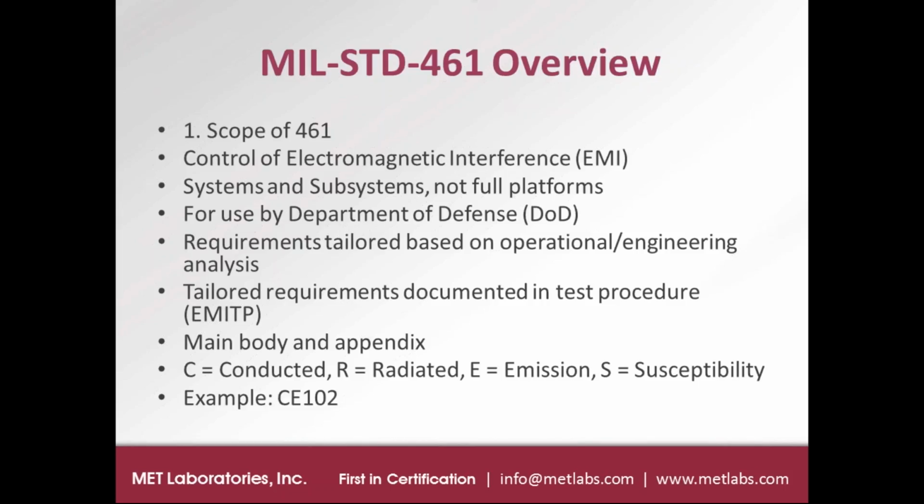The test methods in MIL Standard 461 are named with a five-character name, and the first character, the C or R, represents that it's either a conducted or a radiated test method, and the second character represents that it's either an emissions or susceptibility test method.